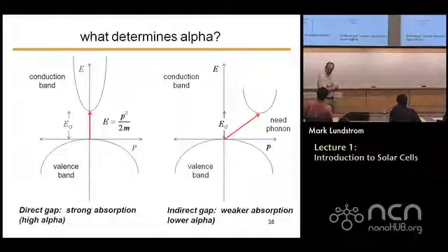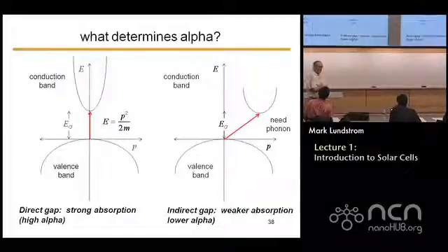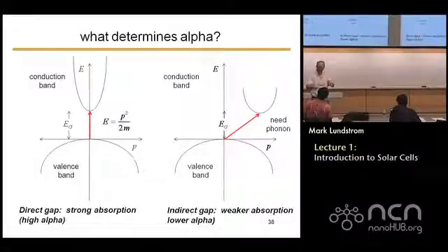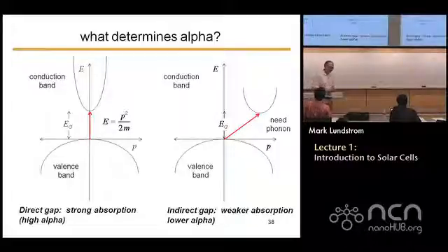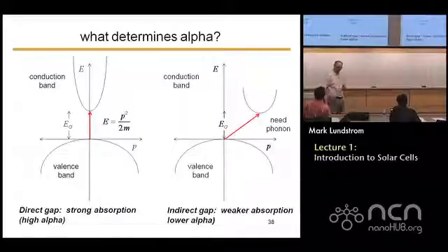And the other question is, what is shunt resistance? Pardon me? Shunt resistance. Yes. It is some parallel current flow path. It might be a defect. You might have a crystal defect that goes right through the junction and just kind of shorts it out. You might have had a pinhole in your process, so when you deposited the metal contacts, a little bit of metal went down and shorted out. There can be all kinds of extraneous current paths that can only be bad, right? Thank you.